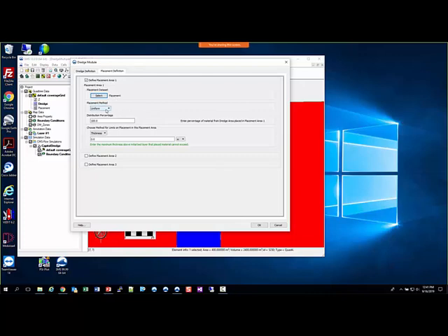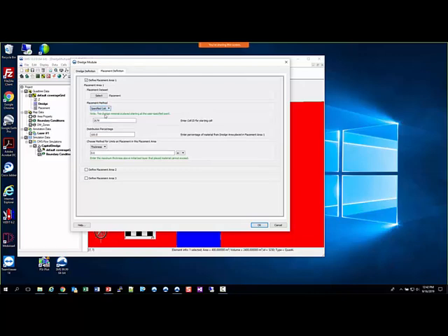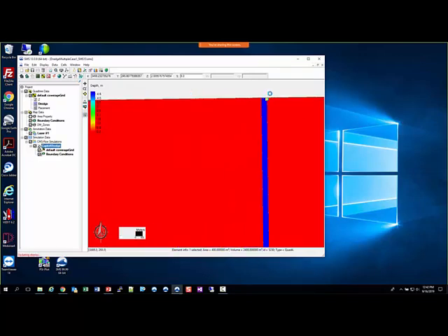We can either place uniformly, or we can start at a specified cell. And so the difference, of course, is for uniform, it places a set amount of material over every cell and then gradually increases the thickness of the entire placement over time. With specific cell, it starts in one corner and it goes up to a certain thickness and then it moves to a different cell. So you may wind up with your entire area not completely covered. So in this case, we need to specify the starting ID for the cell. So let's go and look for that cell number.